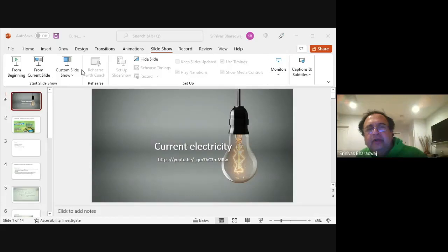So you have plus V, whatever that is, plus I times this 4 equals the net resistance. Equals 0, right? So you can then calculate the current in this, right? Now, if the current here is that, or the voltage drop here is known, then you can look at the remaining parts and use that to solve for the currents. So you have two loops, therefore two equations and two unknowns.